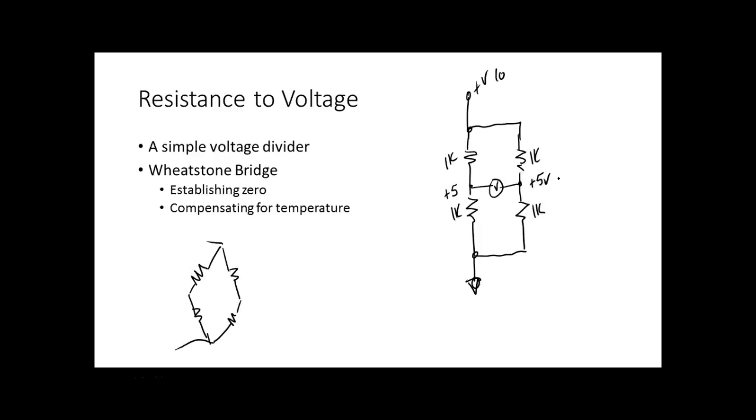My meter would measure 0. There are some people that say 10 volts, but it doesn't. Your meter measures a difference of potential. So even though these two devices are dropping voltages, that meter sees 0. You understand that?